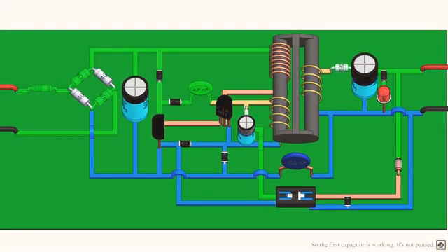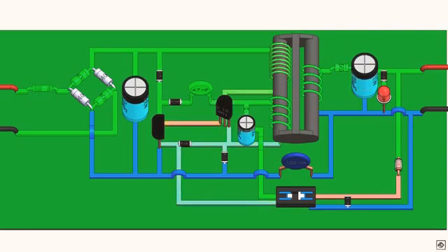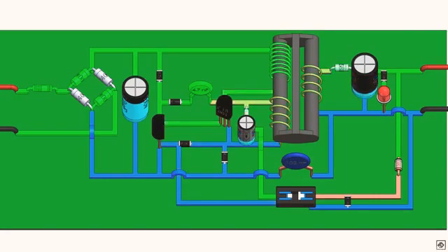Now you would have the question, why not directly convert AC to DC rather than this? This is because, for the normal power supply, which is at 50 Hz, the size of the transformer and the capacitors are large. They cannot be mounted in a small charger like this. Hence, in the charger the 50 Hz frequency is converted to 50 kHz. This reduces the size of the transformer and capacitor required in the circuit. So to change the frequency of AC, first we have to convert it to DC and then again back to AC.